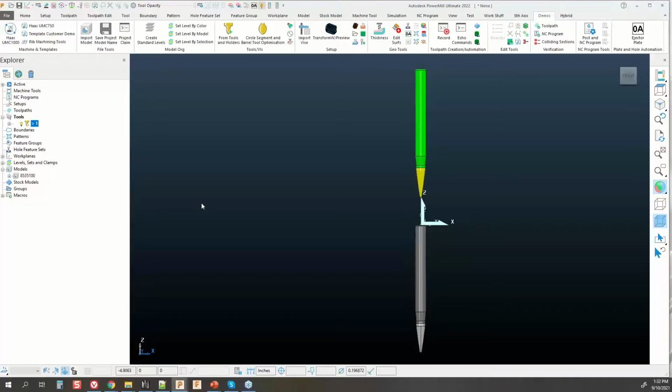Again, whether or not they succeed based on cutter creation and what you're using them for depends on the geometry of the tool. I actually would go in and make two separate ones of these. I have form tool as well as barrel tool cutter with it. If I'm lazy and I want to get through it quickly, or it's just more direct 3D, I'll just create the form tool because it's fast for me to use the macro. If I need to undercut in any situation, I usually go in or use constant Z, not optimized constant Z for the toolpath. Then I will create it as a barrel tool.